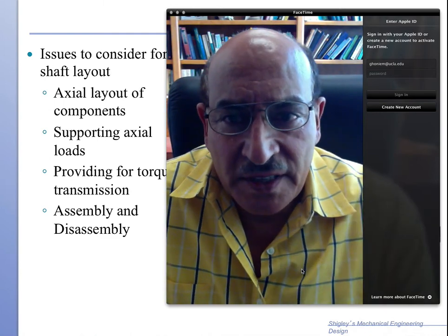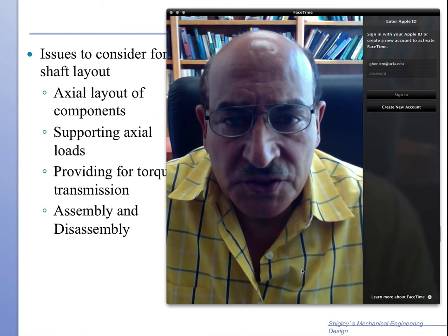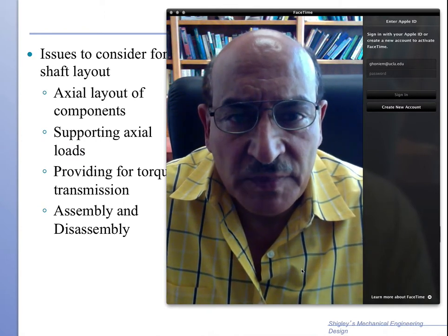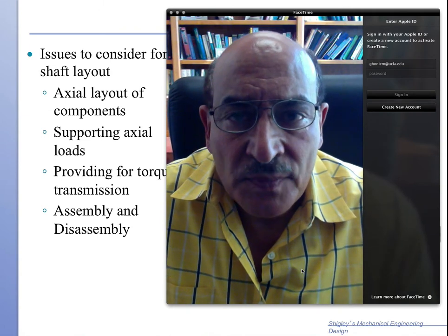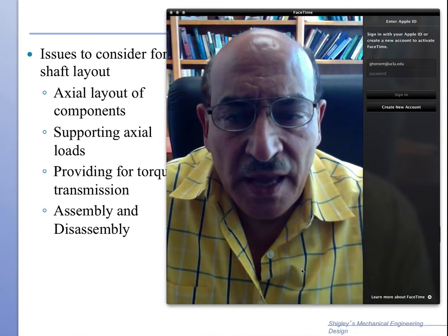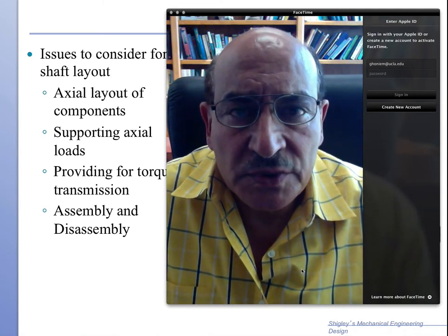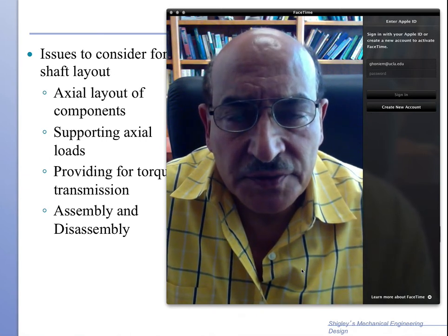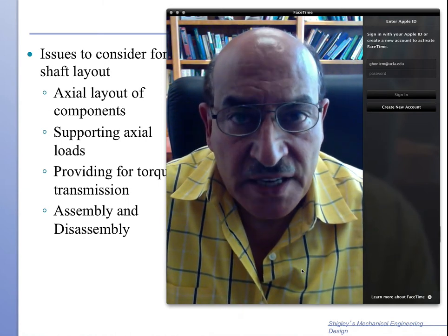So we've ended up in the previous segment talking generally about how you support shafts, and we mentioned that you need to carry axial loads and react those on the surrounding structure. Not only that, but you have to be able to support loading as a result of torque, because torque is needed to transmit the power.